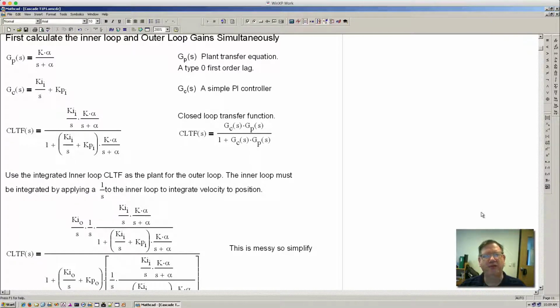I have seen most controllers where the position is differentiated to become a velocity, and they implement a velocity loop using the position feedback. But really what you should have is a better velocity feedback to use on the inner loop. If you have only one feedback device, you really are better off combining the inner and outer PI loops into one PID loop, and I'll show why in a moment. But first, let's just start with the basics.